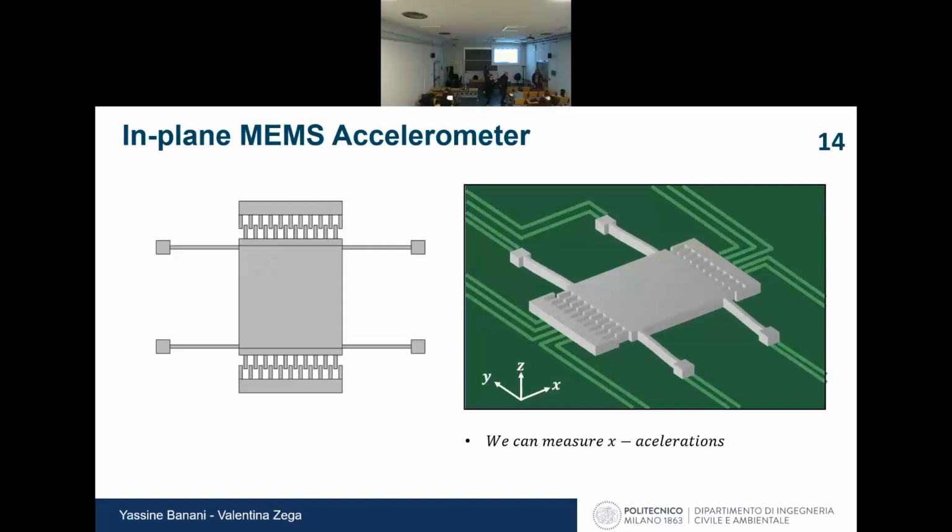In the top direction, you are free, but at the bottom, you have the PCB. So you have some layer you cannot move, you cannot touch. For the sensors that move in the Z direction, can you put them higher? No, we cannot control this dimension. The distance between this layer and the MEMS is given by the fabrication process, so it's fixed. We design them to never touch the bottom surface, so we need to control the displacement.